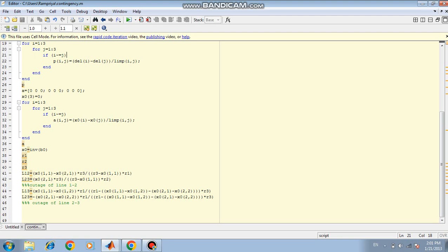In every power system network there is a configuration, and based on the telemetry, breaker and switch status, we can find the network topology. A fast method for performing contingency analysis is this generation shift method. Here the program is written in MATLAB. Hope this is understood to you.